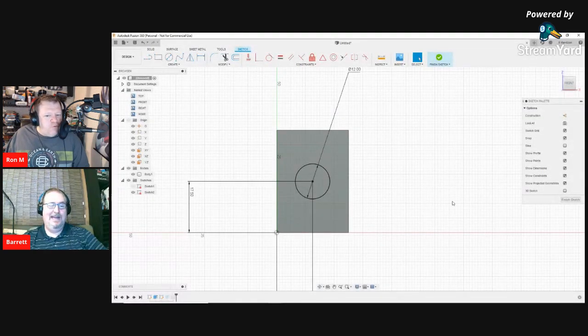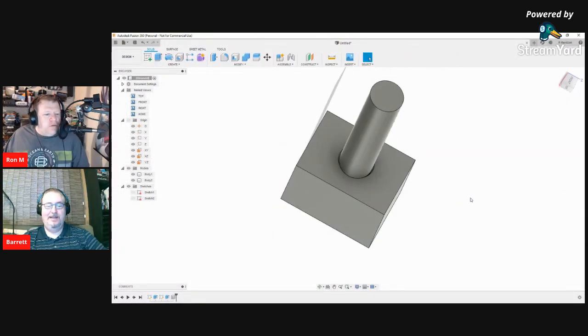Okay. So now, how do I go back to the finish sketch? Yeah. There we go. Okay. So now that we have this handle in it, does it copy what the threads are? Oh. No, we have to add that onto it, and it doesn't actually go in it. If you remember, it's sitting on the outside of it. That's right. So we're going to have to add that thread, but I'm going to show you something handy first.